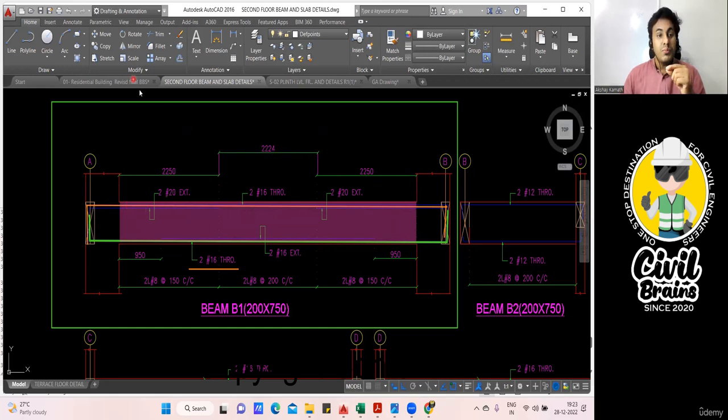Finish. Now, the remaining portion, from this to this, is the development length. You have to check in the drawing what development length is given. Let us say the development length given is 50 times the diameter of the bar, 50 D. Accordingly, you do the calculation. This length you will measure minus 1 cover. This is a column, so minus 40. Then the total development length minus this length will give me this L-shaped length. Understood, no? Very simple. Now, the bottom portion is the same thing. This much is clear.